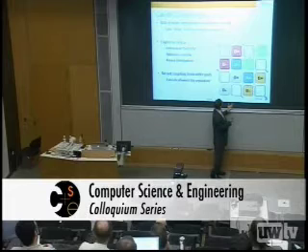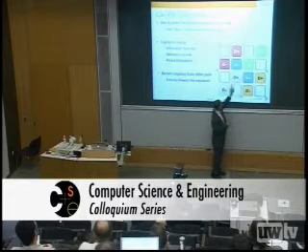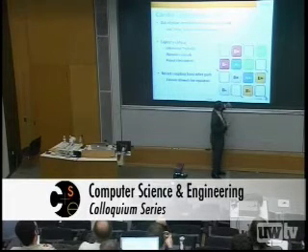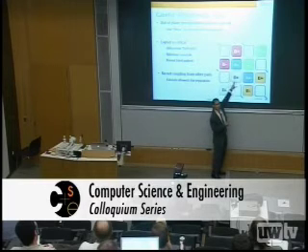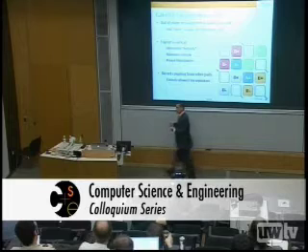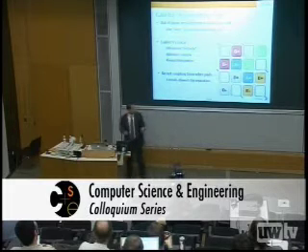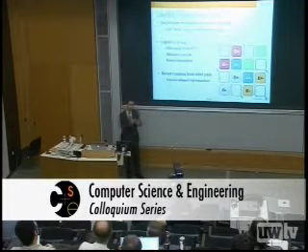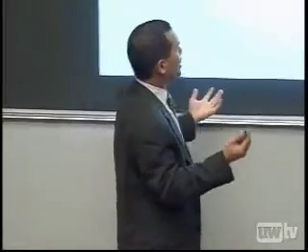By the same token, D bar or D or C bar will couple equally to the bits I'm looking at, making differential mode noise now common mode noise. So with suitable common mode rejection ratio, I can make the coupling effects of separated chips to first order negligible. What this really means is I get some enhanced tolerance to chip separation.